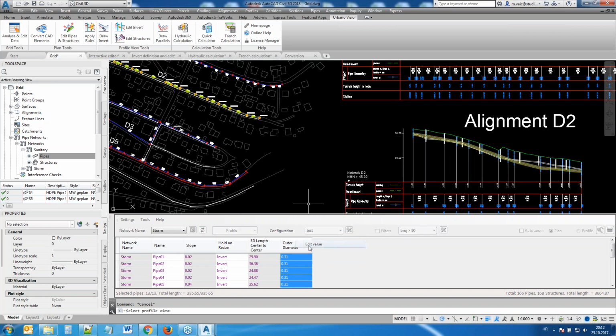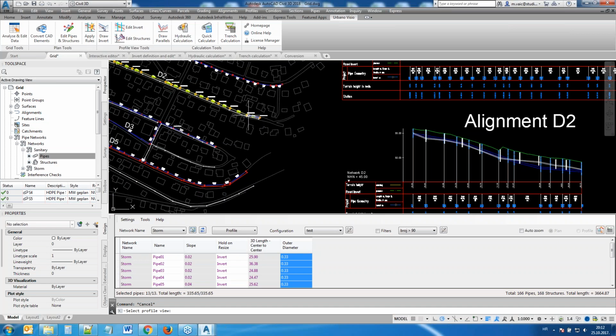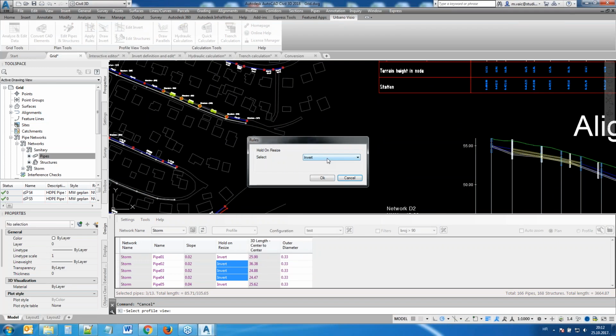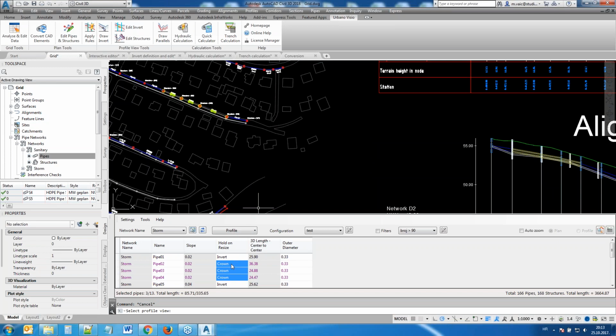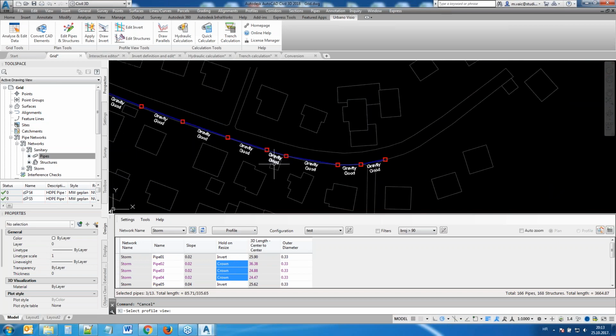And of course, the thing is that you can do it with everything that's editable. So if I want to change the diameter of a pipe, I just again make a selection, right-click, and just change the diameter. Don't want to select everything, just 3 elements, for example? Okay, it's no problem. Just go into edit value. If you have something special like this hold on resize, then again a special editing window will open, and you can edit these 3 elements at the same time.